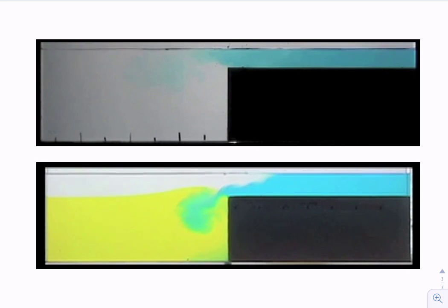Just to labour the point here, we've done some simple lab experiments with these two cases. In the upper panel here, you can see case 1, where we've dyed the water on the shelf to track fluid motion. However, any motion in this part of the tank simply results from the disturbance generated by removing the barrier, because there are no density differences to drive a net flow. On the other hand, when we remove the barrier from case 2, we get a strong and sustained buoyancy-driven flow which creates secondary turbulence and mixing.